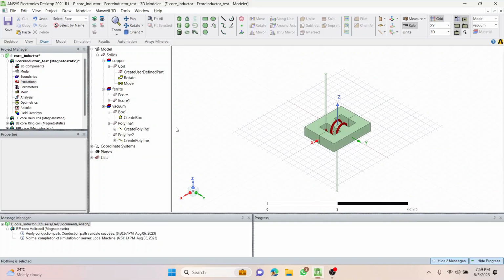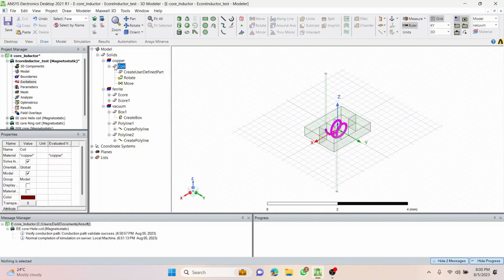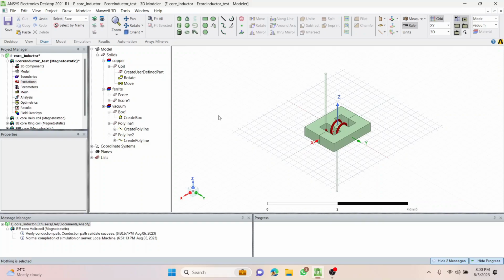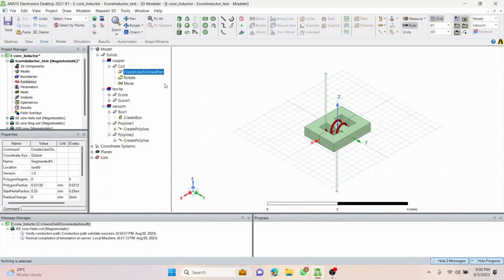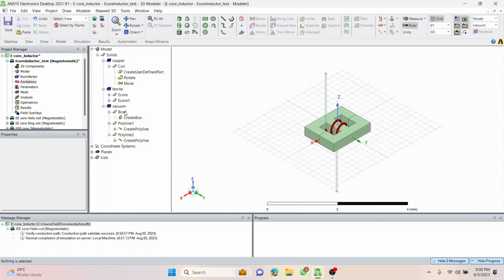So successfully created. Now these line segments or these extensions must intersect our region. Actually they must kind of outgrow it in size. They must be larger than the region itself, because we want certain other operations to be carried out there. So if you remember from our last video, whatever we did, that is what exactly I'm using here, right? So I will draw a box, subtract it, and then just cut it into a very nice plane which will just intersect the boundary. So to make it just intersect the boundary, we need to subtract the cuboids, right?